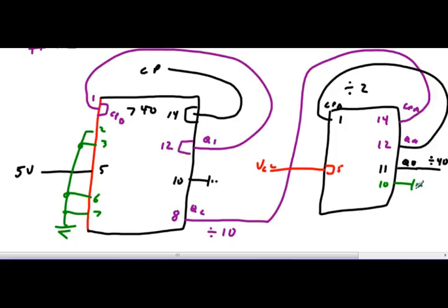I see that that is a master reset. I don't want the master reset to be reset, so pins 6 and 7 are going to go to ground. And that's the way I would do that. Now, what I would do is hook up VCC and ground first, so you get some partial credit, and then do as much of the rest of the circuit as your mind can allow you to do before you punt.